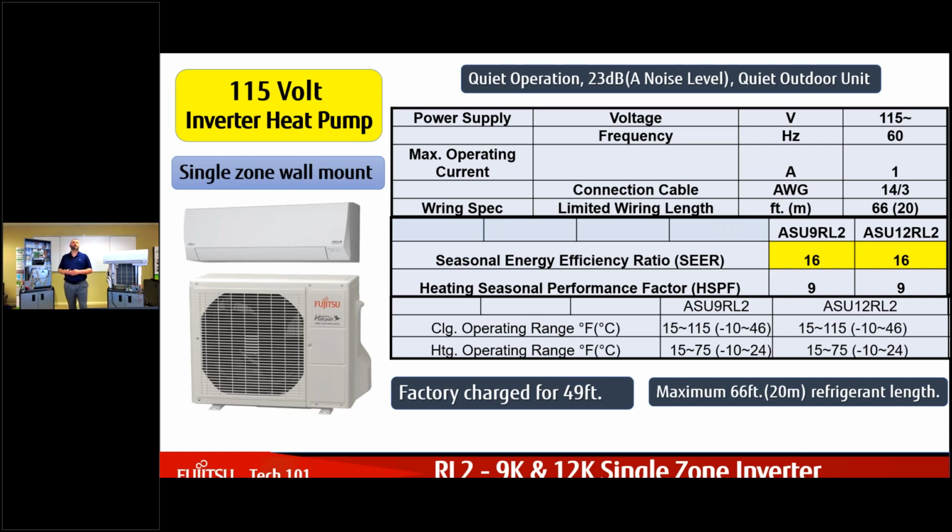So if we're at -5 or -15, am I getting 100% out of this? Is it going to be diminished? I know there's more detail coming up. Yes. On those extra low temperature heating units, we will be able to give you that nameplate capacity down to -15 degrees, and we start to lose capacity after that.